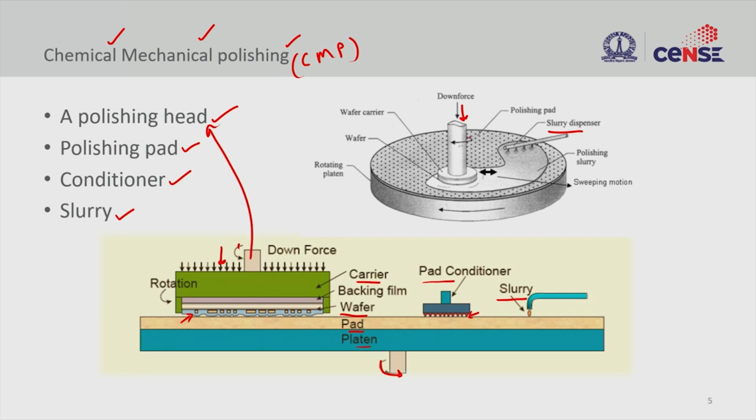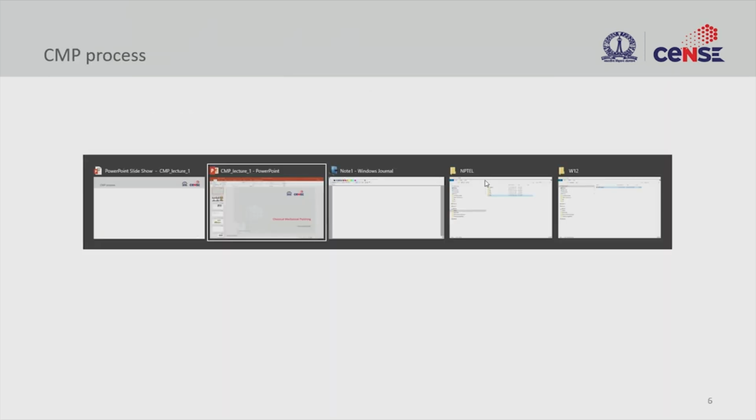So you have the head which is rotating in one direction, and your pad is rotating in one direction, and then you also have the spindle or the head rotating in another direction. So the rotation direction and also the configurations vary from method to method, but in principle you want at least one of these elements moving so that you have friction between the wafer surface and your pad to create material removal.